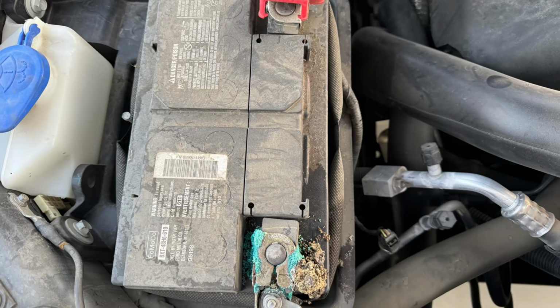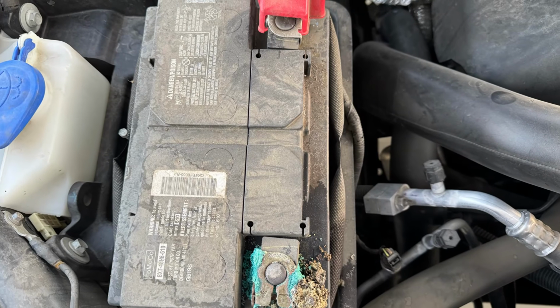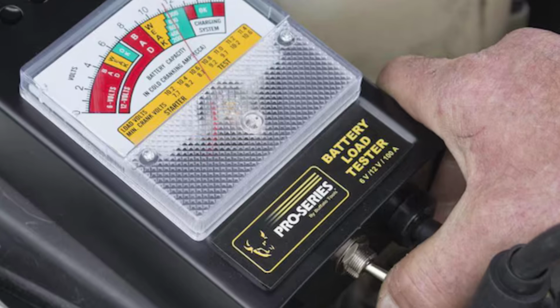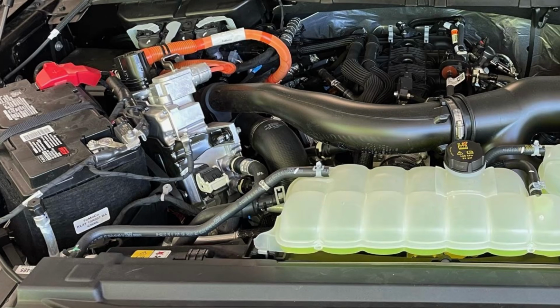There are basically 4 reasons for the U0415 code, and some of them you may check and fix on your own. First of all, check the battery health with a load tester. If the battery is low, the ABS module may fail to deliver proper data to other modules in the system. Also, it makes sense to check if the main ground point is tightened and doesn't look corroded. This is the ground point that you can track by following the cable from the negative battery terminal.